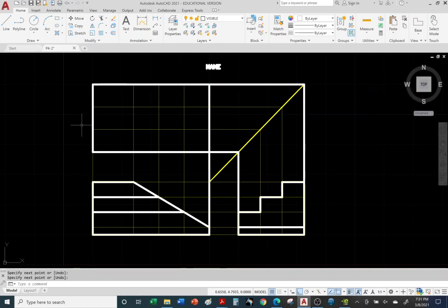Okay, so we know that our top view is inside this box. Okay, so I can go ahead and now shorten these to the correct length. I may need to go in and do some adjustments, but there it is. So everything is supposed to line up. As you can see, escape to deselect. Let me get rid of the evidence that I cheated. And delete. Okay, so that's how straightforward it is: you create a box, use orthographic projections, use your 45.